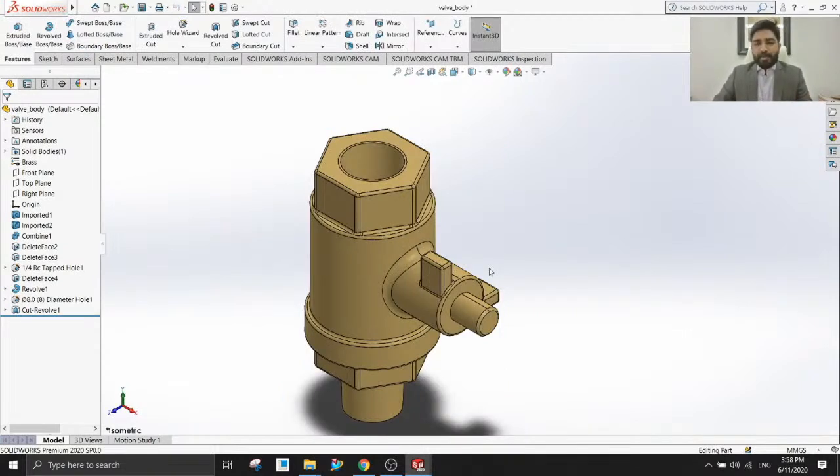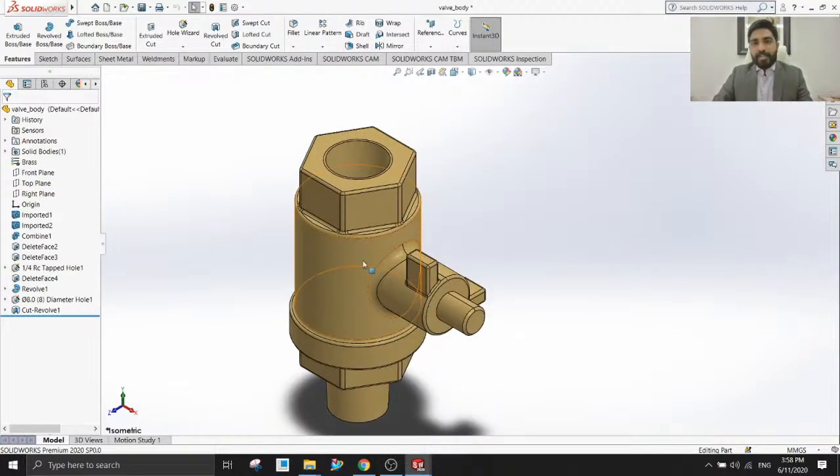Next, what we are going to discuss is the orientation of a body that we create. In SolidWorks, unlike many of the other 3D modeling software, the up vector is given in the y-axis. In SolidWorks 2020, they have added a provision in which we can change the up vector from the y-axis to the z-axis. Let us see how it is done.